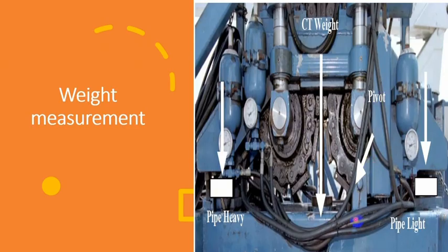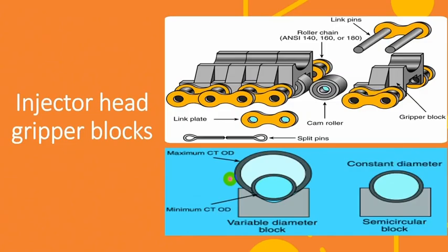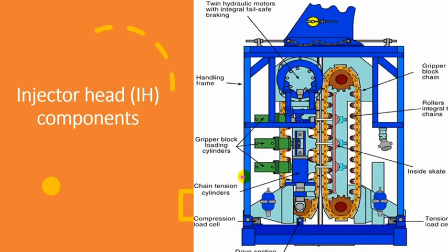This pivot point makes the injector rest with its weight on these two load cells. One will measure the tension and the other one will measure compression. As you can see from here, this is a compression load cell and a tension load cell with the fulcrum point here. So your injector in cyan color will rest on this load cell and this load cell.